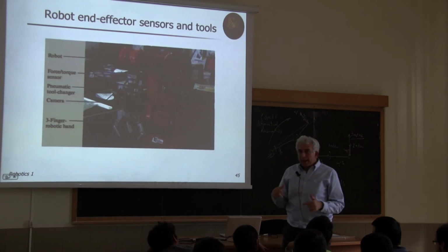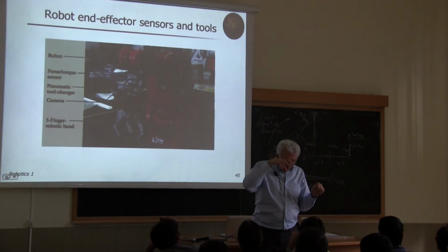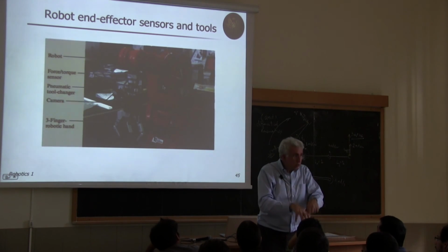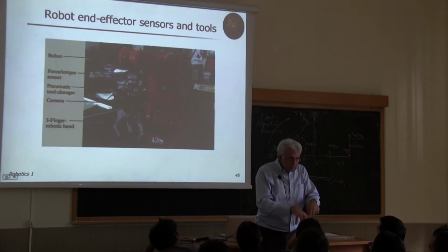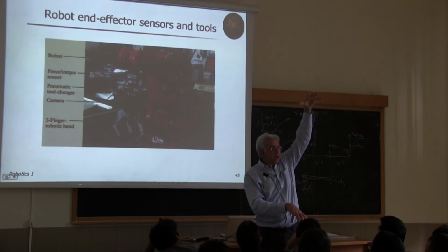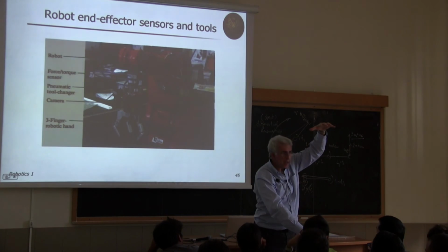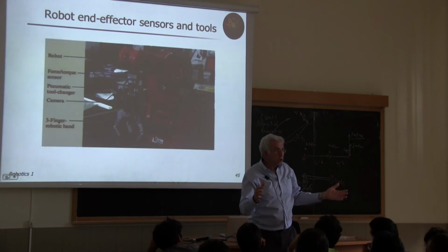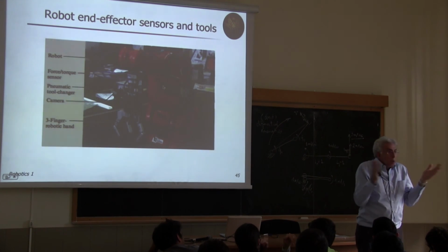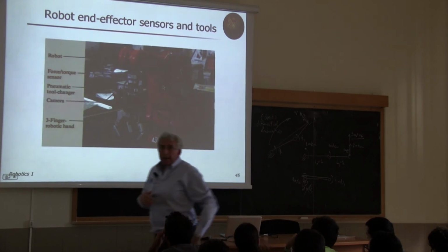Okay? On the other hand, it's very convenient to have an eye-in-hand situation, because if I'm grasping something, I will get closer and my camera will continuously view the object so that I can be very precise, driven by the camera sensor. If I have a camera overlooking the object, the scene, and I'm going with my robot to grasp the object, at some point the robot will occlude the visibility to the camera, and I'm going open loop. Okay? So there are advantages and disadvantages.